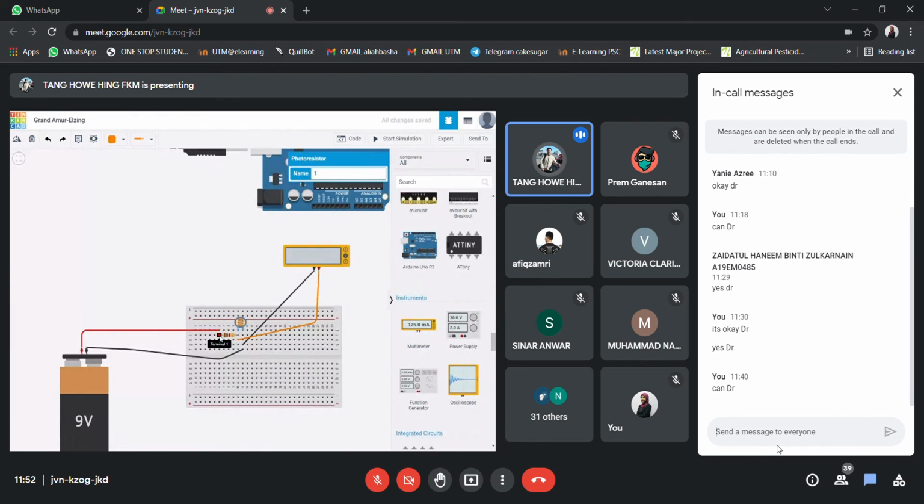Input goes to these resistors, and output comes from the connection. Therefore, by using this form of a voltage divider, I can convert the resistance change into a voltage change, right?